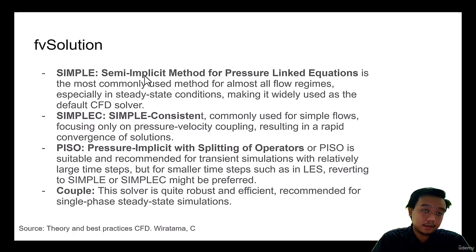But if we want a faster solution, or a better solver, we use the PISO solver, which is the Pressure Implicit with Splitting of Operators. This PISO is recommended for transient simulation.